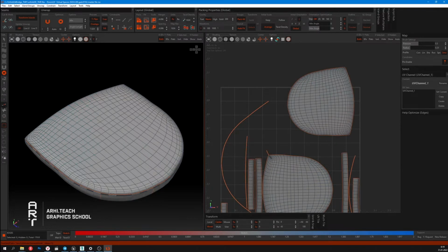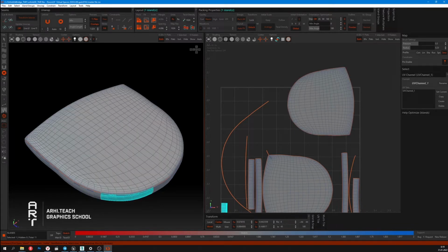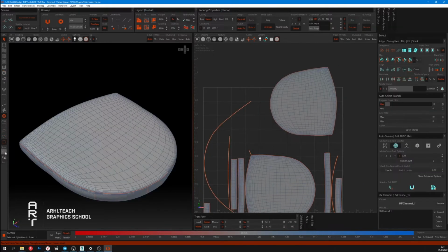Then we've got Vertices, Edges, Polygons and Model Elements tools. These tools are applied by pressing the hotkeys F1, F2, F3, F4. These 3 tools are used the most: Edges, Polygons and Elements. Then we've got the highlighting tools, such as Box Selection, freeform selection or circle selection. I don't use the remaining two symmetry elements.